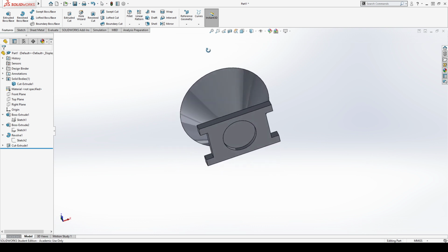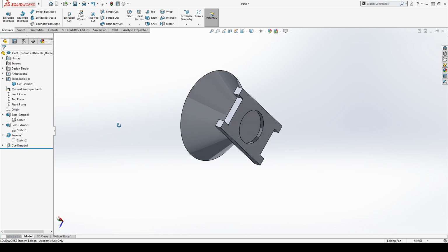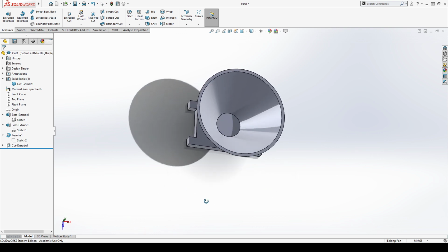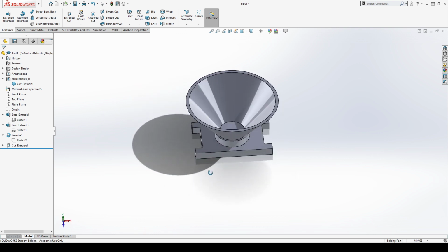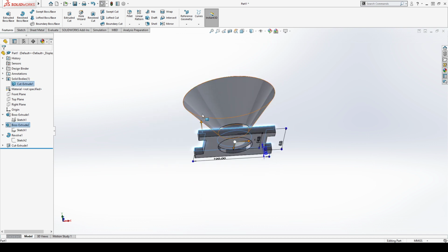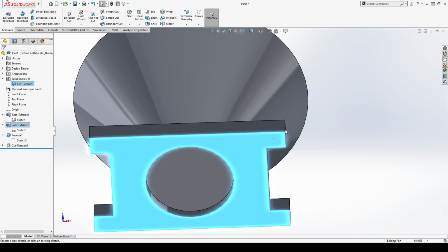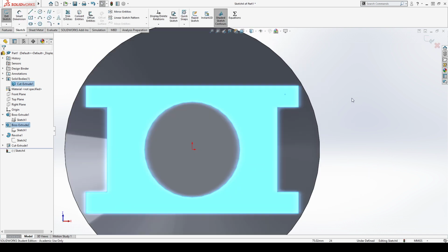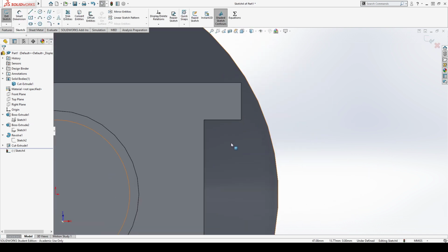And then the only other thing that I wanted to showcase here, let's see, what would be a good part here to show? Oh yeah, so I'm going to make one of these tabs here. So I'll sketch from the bottom just because it's easiest to get to. I want to round out this corner here. I could do it with a fillet, the fillet feature itself, which we'll get to later.